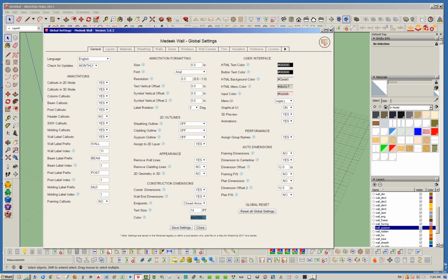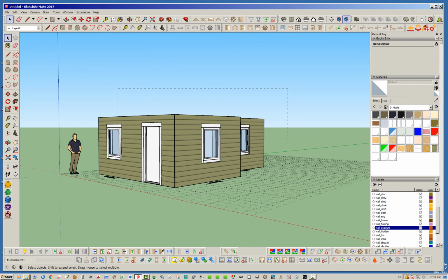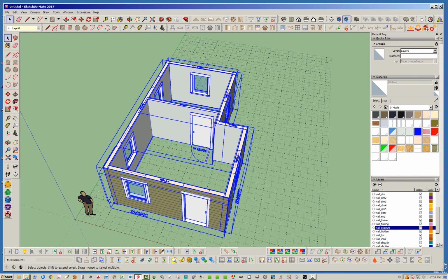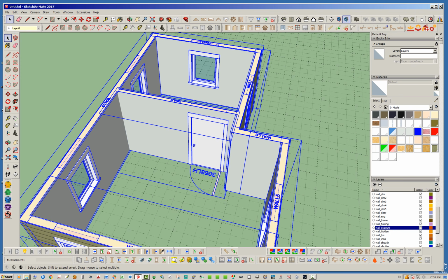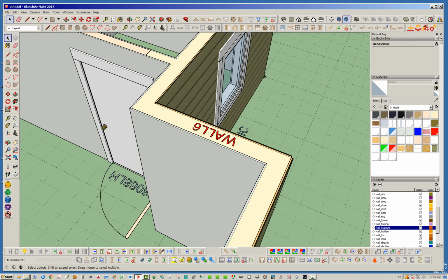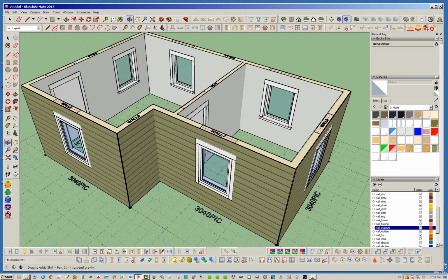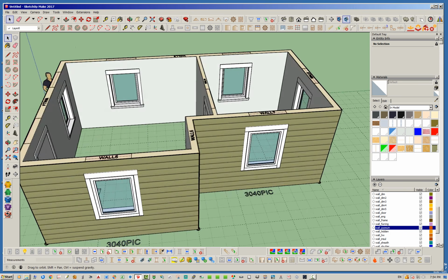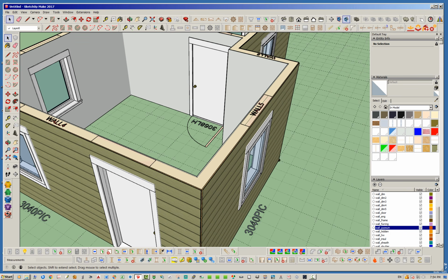This is just a global setting that you apply globally. Go ahead and hit update on that, close that out, and now if you regen all these walls, so I'm going to select them again, and then I'm going to regen, and that should regenerate all these walls. And now you'll notice that those edges have gone. So what's happening when you turn that hide wall line option on, let's turn that gypsum back off, we can take a better look at that.